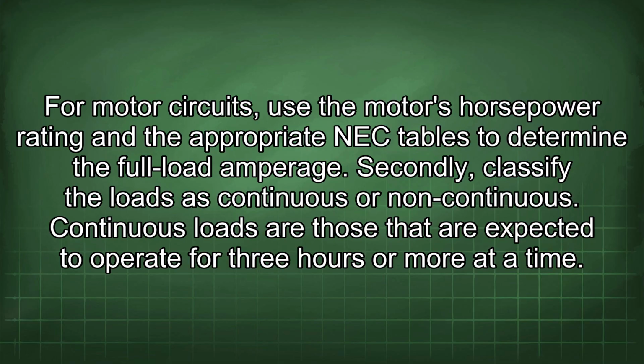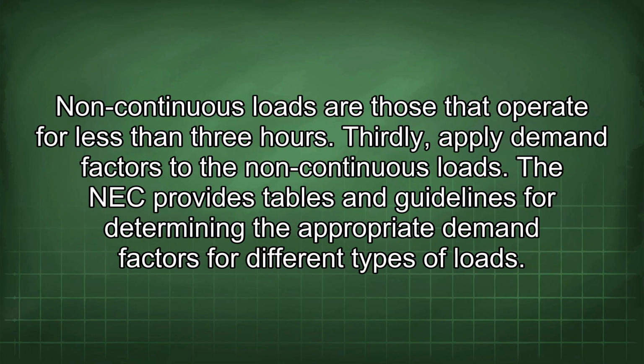Secondly, classify the loads as continuous or non-continuous. Continuous loads are those that are expected to operate for 3 hours or more at a time. Non-continuous loads are those that operate for less than 3 hours.